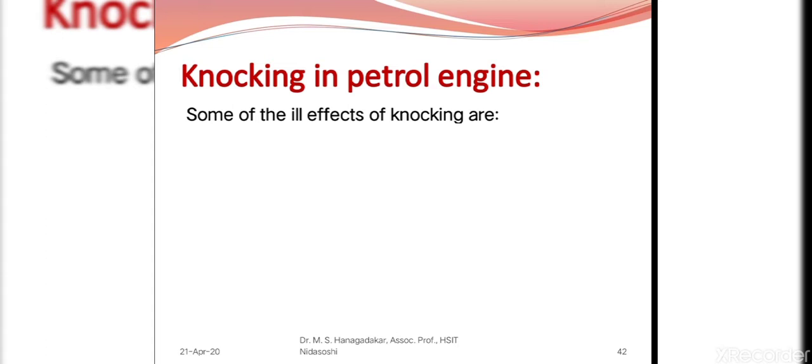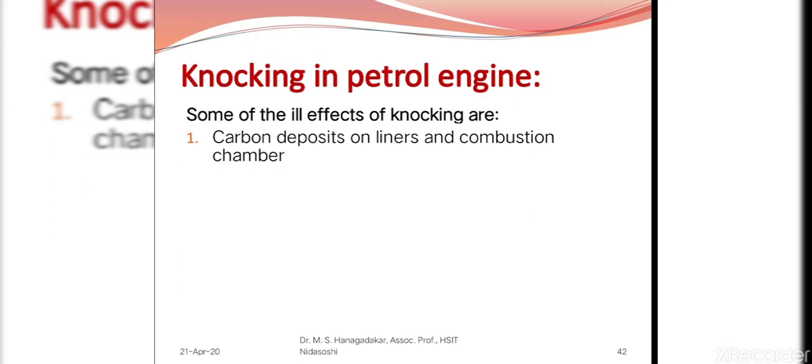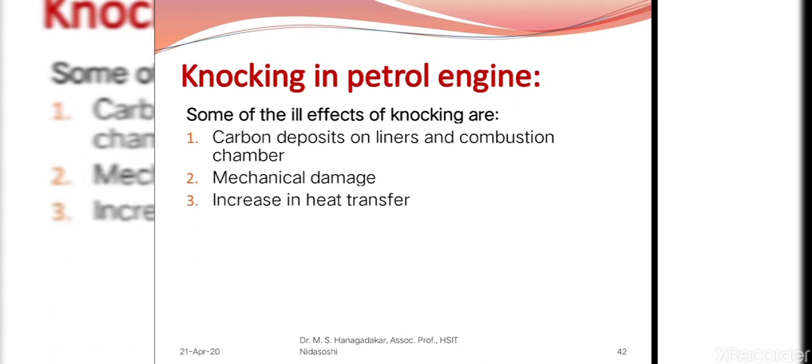So what are the problems to the engine if there is knocking taking place? Let us discuss now some of the ill effects of knocking. Number 1, carbon deposits on liners of the engine and combustion chamber. Second, mechanical damages to the cylinder as well as the piston and spark plug. There is an increase in the heat transfer.